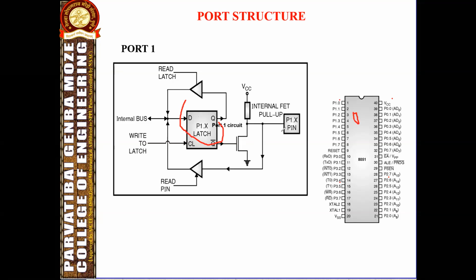All the ports upon reset are configured as input ports. If all the ports are reset, meaning we have configured them as 0, then they will act as input ports. As the functions are multiplexed on the same port, in order to decide which function is supported, we need to see how the circuit is connected and what software commands are used to program the pins. There are 4 ports required for I/O operation out of the 40 pins.